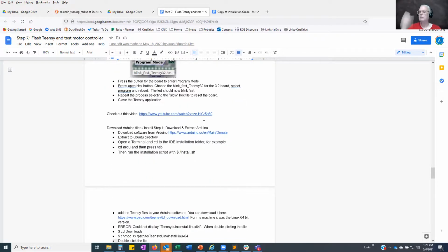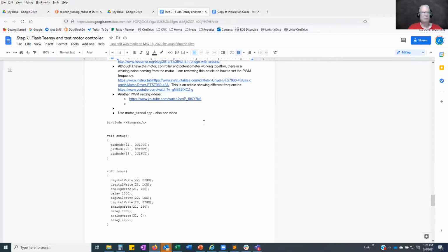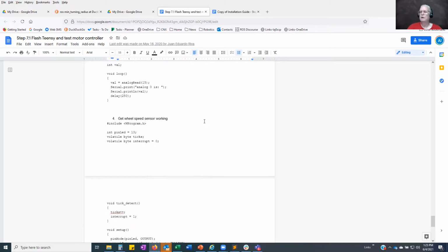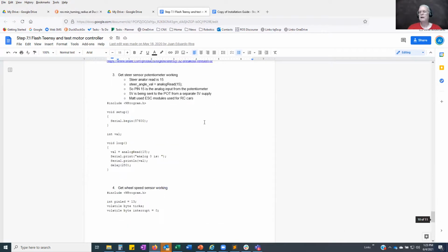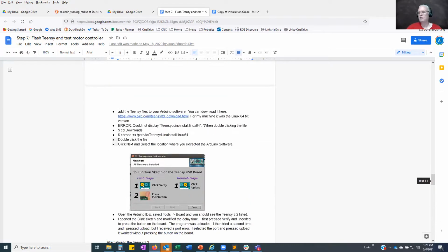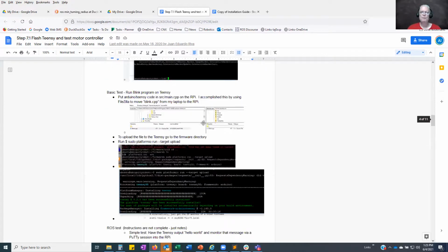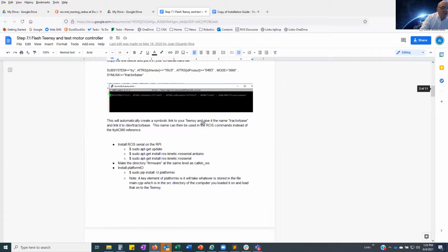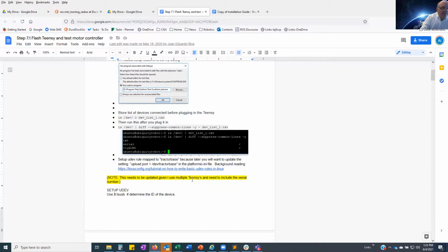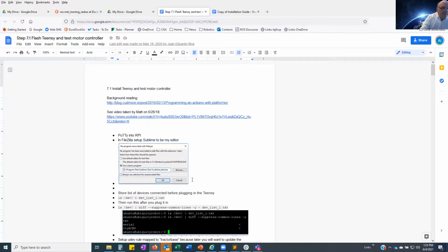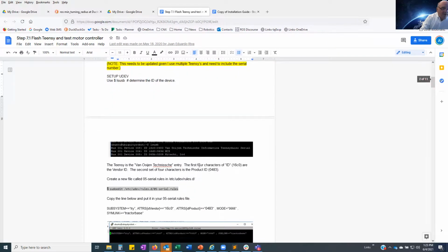Actually you do have a slight control there, because under UDEV rules, you can say, number one, it must be an Arduino. There's something in there that tells you what type of device it is. So you do that, and then you say if it's plugged into the first port, then it's going to be, say, the laser scanner or whatever it happens to be. If you look on G Drive and search on Teensy, you'll see some descriptions about how I set up the UDEV rules. I mean, here's one of them.